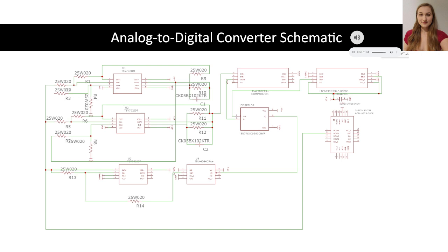as a feedback loop. Then it goes to a decimation filter, and this takes it from the oversampling rate that we have in the megahertz down to a much more reasonable value. This allows for the signal to be much clearer.